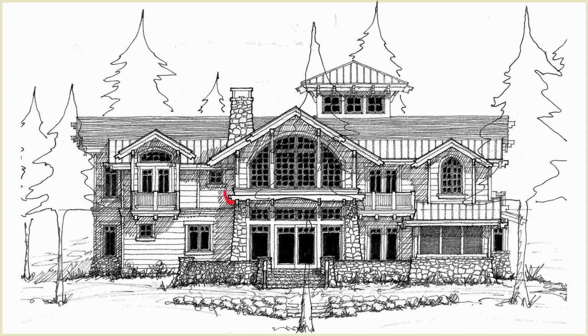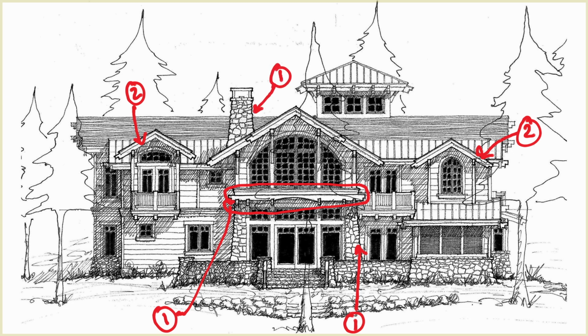I would say right there, around here, that's probably number 1. The roof there is probably number 2. That's also a number 2. This edge right there is probably a number 1 still. That there is probably a number 1. And we work our way back. The textures, that's probably number 4. Up here, that's further away, that's probably number 5. The trees themselves are probably more like number 6s. Even though they're in front, they're done really light so they don't distract too much from the actual elevation view. Do you guys see how these line weights are coming into play?